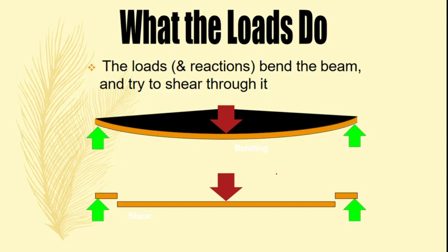Means if we want to design a beam under the strength criteria, we have to know the maximum shear force and the maximum bending moment of the beam. And if we consider the rigidity or stiffness criteria, then the deflection and slopes are used in the design of the beam.